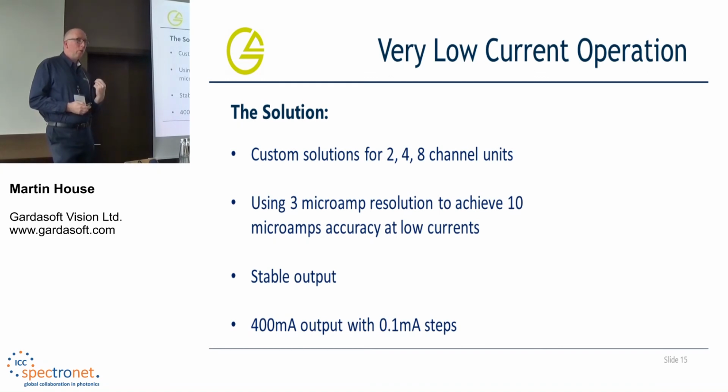And then when you're using your Linescan application, you do need to think about making sure that you're not getting any crosstalk in your illumination. And again, you need to go back to thinking about the fast pulsing. And the thing about lighting control is there is no one simple answer. There are many little factors that can cause a problem. And Sophie will agree, you know, the customer will look at the data sheet of a product and think, solution. They switch it all on and it doesn't work because there's maybe one tiny parameter that's been missed out.